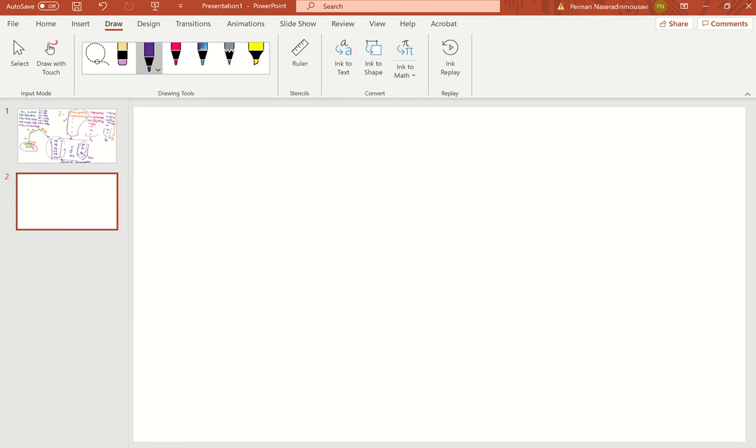So I say theta 1 is A1 sine t, which is periodic, going forward, backward, forward, backward. So theta dot 1 is going to be A1 cosine t, where t is time. And I say theta 2 is A2 cosine t, which has a phase shift, so theta dot 2 is going to be minus A2 sine t.